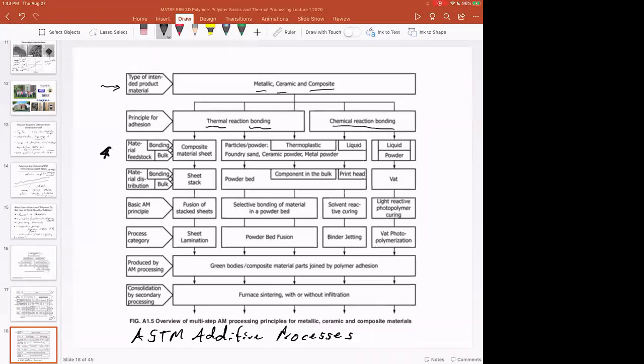And this is what a lot of materials companies are interested in. So if you go buy steel, or aluminum, or polymer, generally you get a bar stock or a sheet stock, or in the case of polymers, you get pellets. But there's been a whole proliferation in the materials market for materials in the form factor that can be used in additive. And so what's the particle size distribution of the powder? What's the size of the filament? What do the pellets look like?